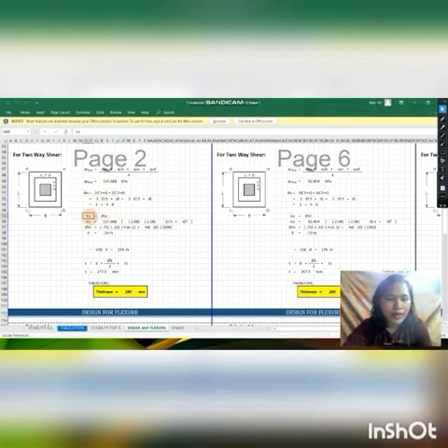So next, we have here again our equation, VU is equal to VC, to equate the two formulas to get the value of D. For our VU, we have the formula of QU average times the area minus the side of the column, or C1, plus D, squared.